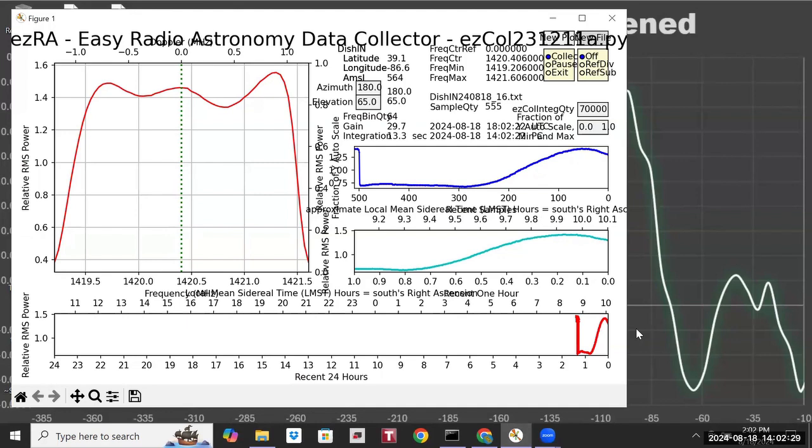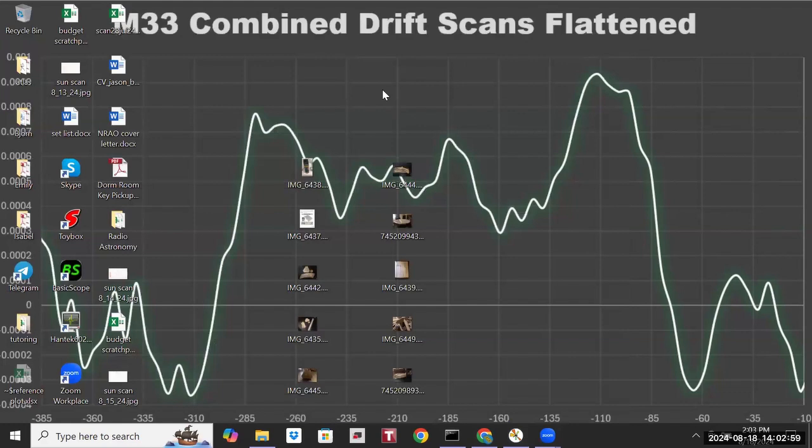So I did set up and I did some preliminary feed adjustment to maximize the output, and then set it up to transit at local noon. And I'm just doing a total power scan, mostly to test the beam of my antenna, and it's looking pretty dang good. My early tests a few days ago were not nearly as good because I didn't have it adjusted yet. So just to give you an idea of what I'm doing as far as my dish is concerned.